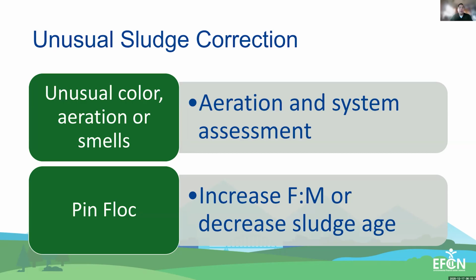Now, if you start to have unusual smells, that could be from your sludge going septic, that could be from dead zones in the treatment process where sludge is again treated, or it could be toxic loads to the system. Those septic loads, like we said, can be from dead spots in the collection system, or if your lift pumps aren't timed correctly, or similar situations with too much sitting water. Now, toxic loads are usually due to unusual chemicals from commercial or domestic sources.